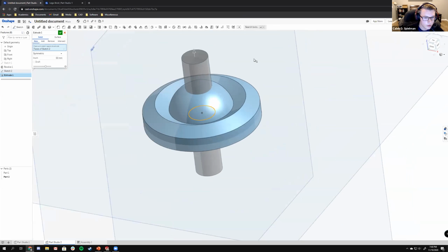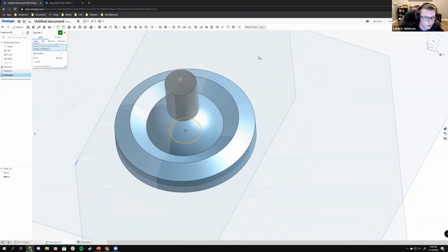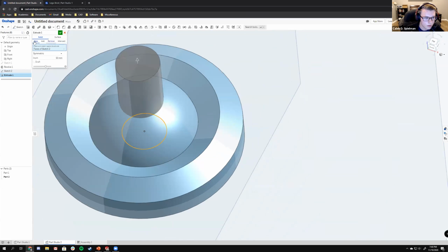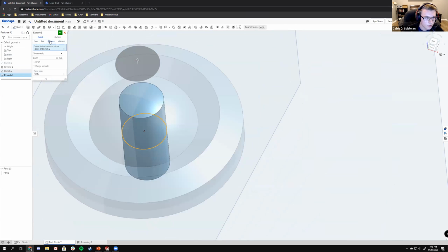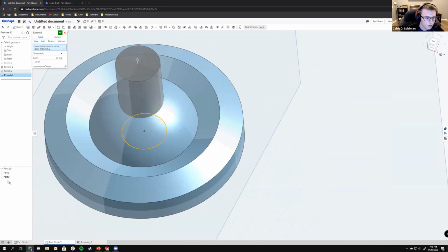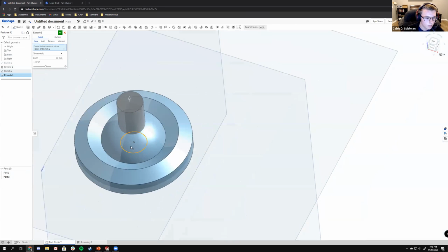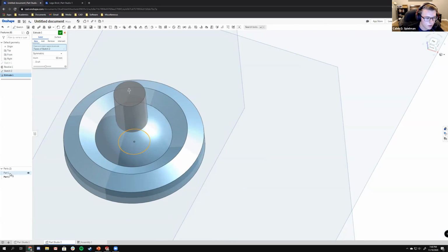So an important distinction between different extrusions on different contours. So these features, I don't know if they're features really. We have new, add, remove, and intersect. Intersect is just a Boolean operation. New creates a new solid body, which Onshape defines as a part.